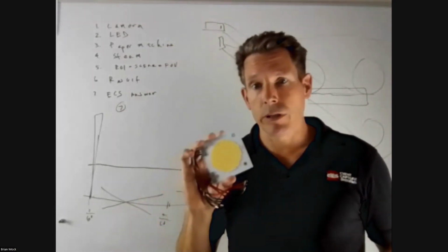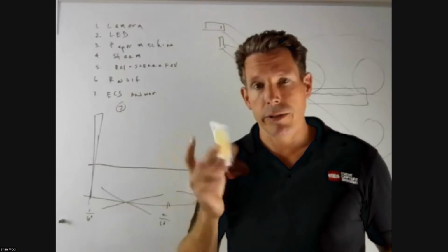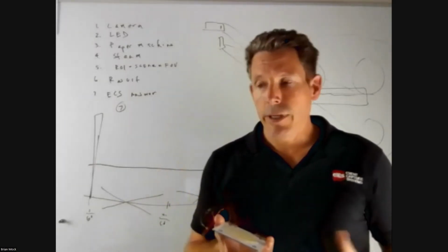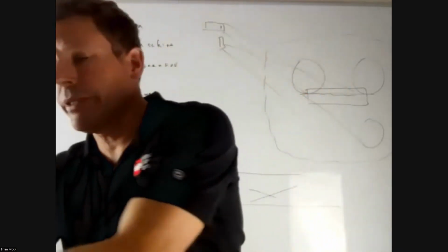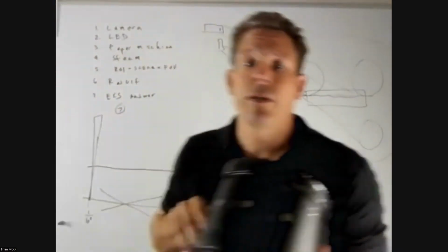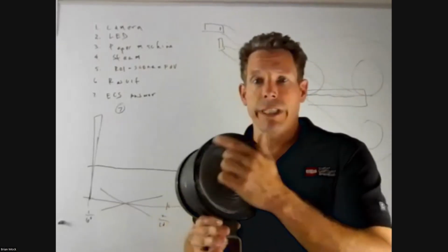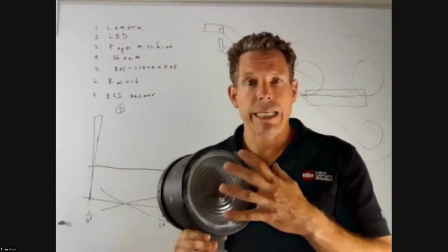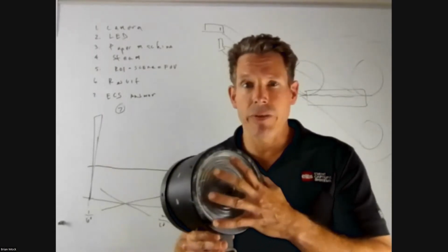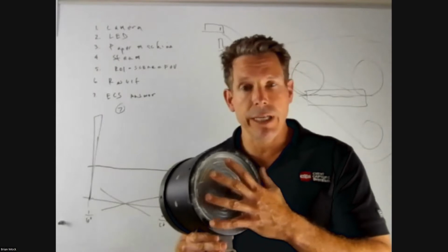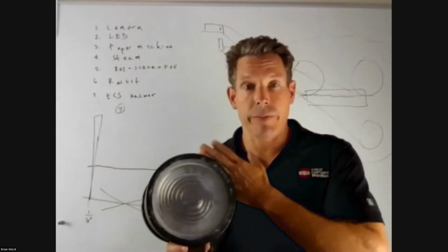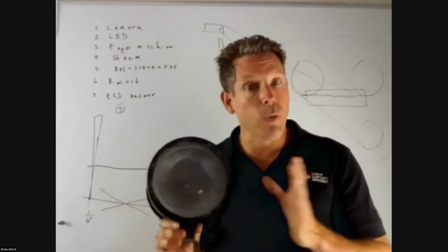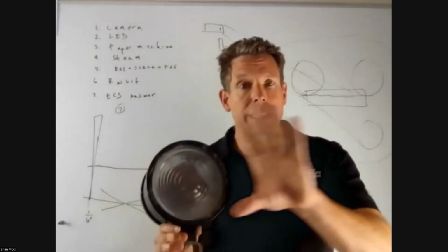And then number two, it's another thing you don't notice on this. There are no electronics on this chip whatsoever. So this is the LED built into the body right here. Notice the Fresnel lens right here. Fresnel lens is the technology they use in lighthouses. That is a completely even way to distribute the energy. And the way you focus it, it's the distance away from the chip on board that makes it a wide angle or a more narrow angle. But within that wide or narrow, it's perfectly even lighting.